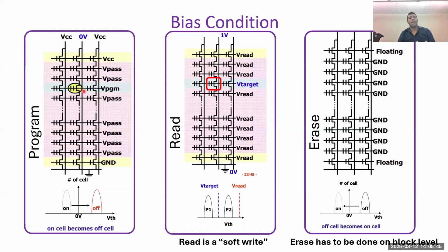So the NAND understands that the biasing condition should be modified based on the ordering of the cell. Our firmware will tell the NAND, you can write only this cell right now, and based on that, it will select the voltages. Every time you write to one word line, it will affect the other word lines. So we account for all of this while we select the biasing conditions and figure out the order of the cells we have to write.